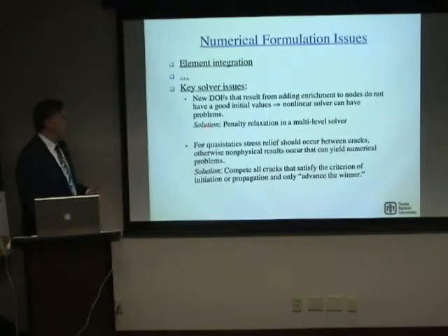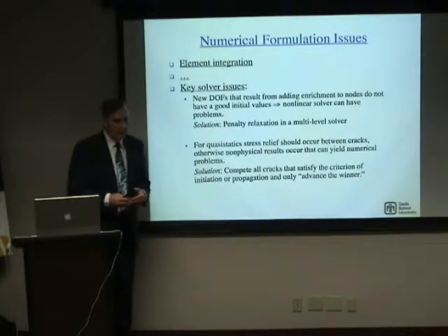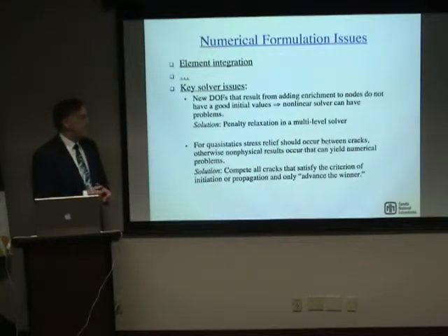So a solution that I've come up with, when I was doing this with relatively coarse meshes, is what I refer to as penalty relaxation. Typically in penalty methods, you're thinking of using a penalty addition. Say if you think in terms of some functional to your problem, you're bringing in a constraint that you want with some penalty parameter, and as you make that penalty parameter greater and greater, you satisfy the constraint in a more rigid way, or more consistent way.